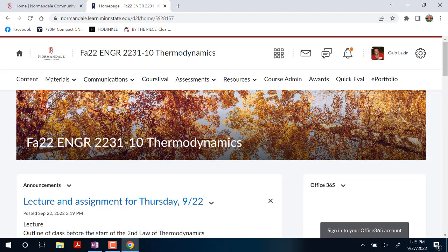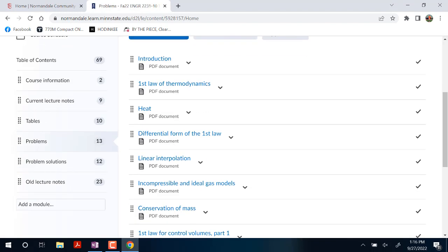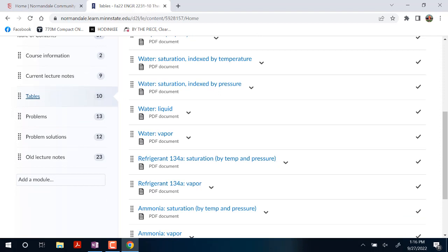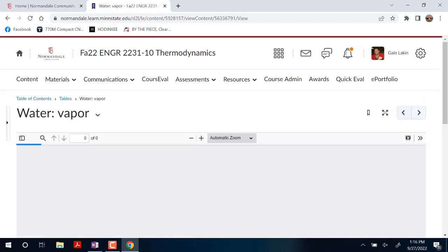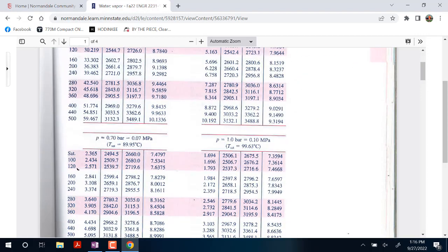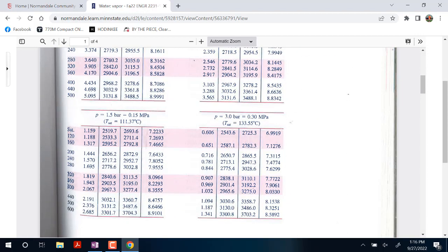We're looking for that enthalpy we just calculated and 0.28 megapascals. This is water. We're looking for steam. So 0.3 megapascals is what they give us in the table, and we're looking for 2.907 times 10 to the third.